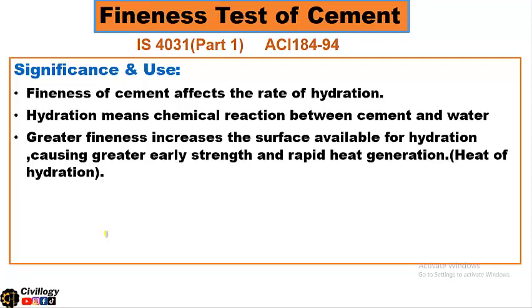Therefore, there is a drawback to having too many small or tiny particles in cement: it causes the cement to set very quickly, which leaves no time for mixing, handling or laying the cement. In order to lengthen the time it takes for cement to cure, cement must be made in a variety of particle sizes.